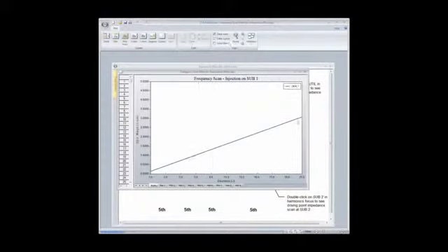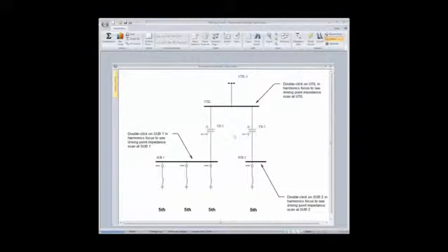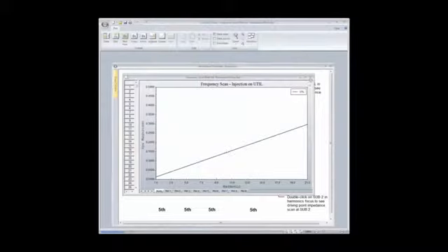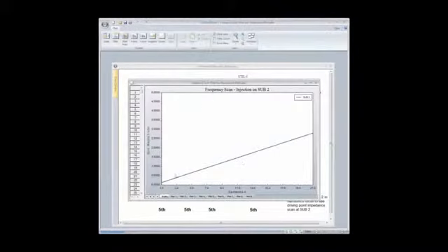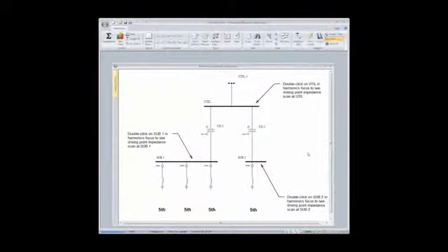What this is saying is, as frequency increases from the 1st to the 21st harmonic, the impedance of the system is going up linearly, which is true because X sub L in the transformer is 2 pi f L, so it's a linear relationship with frequency. In other words, it's a linear increase with frequency. Also, the driving point impedance of the utility up here is pretty much inductive, and because of that, we get that nice ramp. If we were to look at any one of these locations, we're going to see the driving point impedance is a ramp.